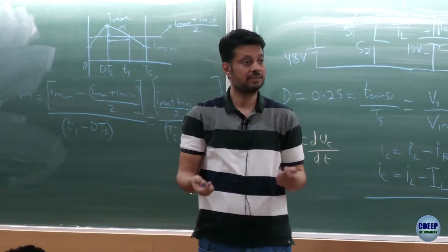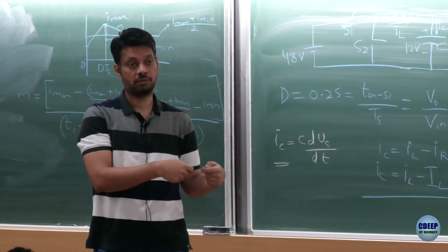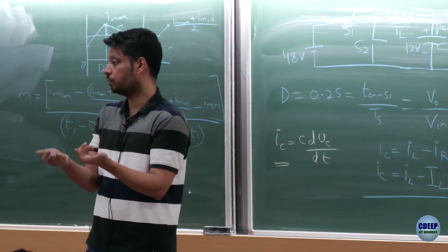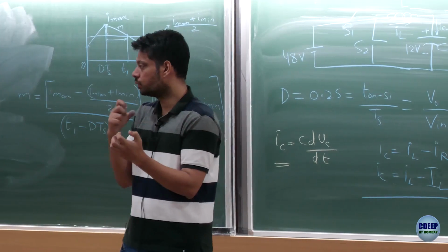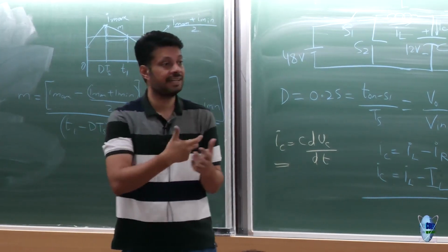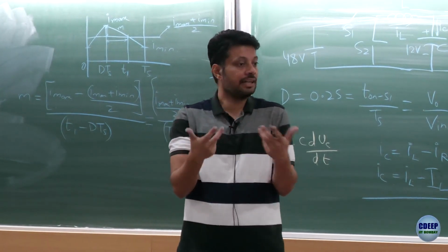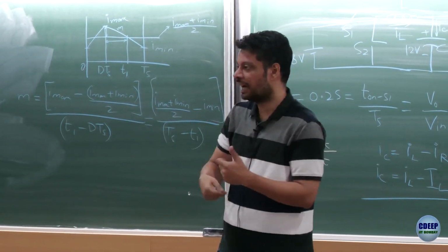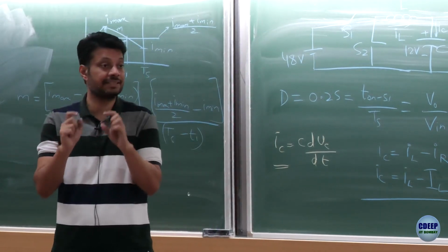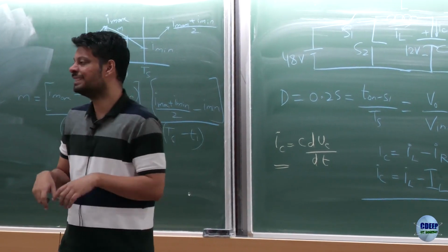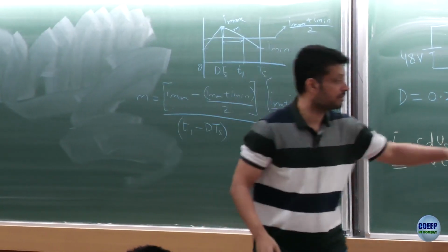So what will happen is this would create problems with your loads, right. So let us say fan load, right. So now the fan load would have this oscillatory torque and it would make sure that the fan degrades much faster. Similarly electronics, right, electronics may not accept this kind of a highly variable power supply. So all these loads would expect a very nice clean power supply. Now when we say clean or when we say nice power supply, how do you quantify it? You quantify it in terms of ripple.